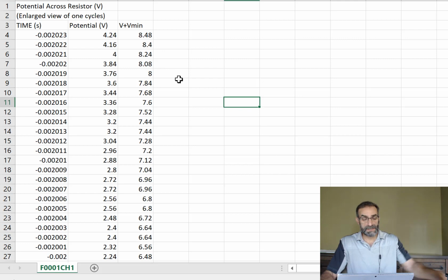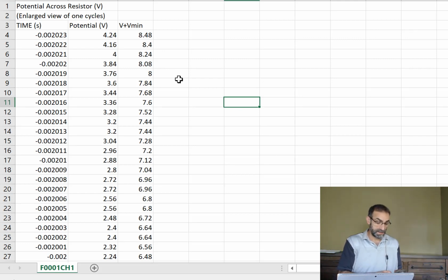and I'm just going to use my calculator. It's telling me e to the first power is 2.71828. I can take 1 over that. I get 0.36787. And I multiply that by 8.48 in my case here, because my data is a little different than yours will be. I got 3.12. So I'm looking for the voltage, column C, to be 3.12 volts.